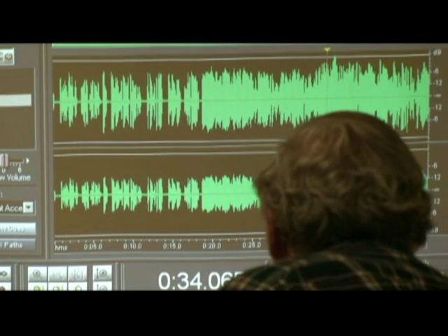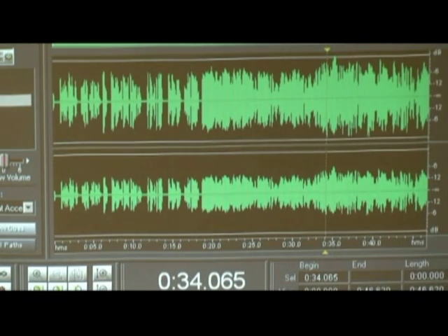It won't go that high. I can't overload it. However, did you hear the distortion when I had the speakers too loud? That's basically what you're going to get if you record too loud. Believe me, in trading, I'm sure all of you have had audio tapes that you've collected or traded with other people, and you get them in and they sound just like that. It means somewhere, somebody along the line just overloaded that level. They thought they were trying to get it as loud as they could to keep it from picking up noise, or maybe they weren't paying attention to the level.